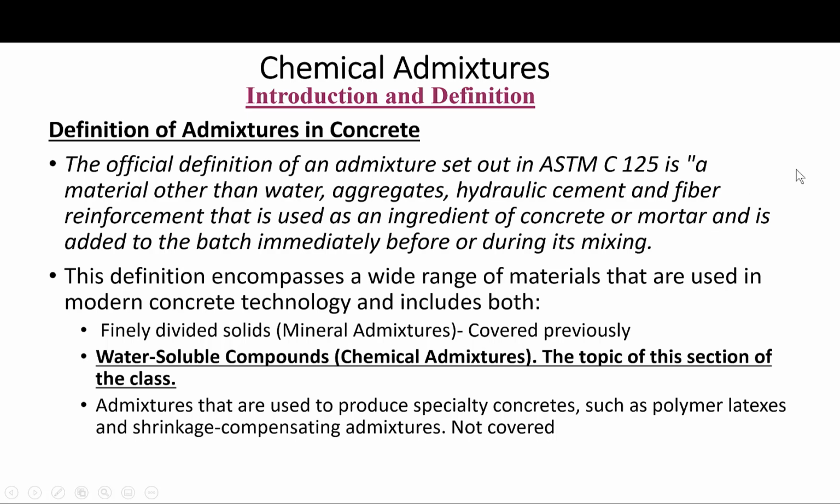All right. This definition encompasses a wide range of materials that are used in modern concrete technology and includes both the finely divided solids, which again, the mineral admixtures we covered previously during the discussions about the supplementary cementitious materials, and also the water-soluble compounds, which are the chemical admixtures.